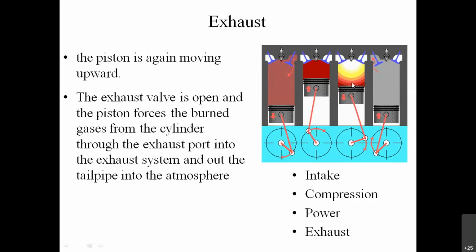So it works similar to the SI engine. The only difference is that in the CI engine, instead of a spark plug, we are using fuel injectors. In case of the SI engine, we are taking in the air-fuel mixture directly, and that mixture is ignited by generating a spark using the spark plug.